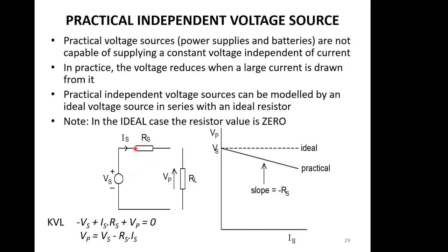And as a battery goes flat, it doesn't really go flat. What happens is this resistance gets bigger inside the battery, because the battery just has trouble getting the charge to run out of itself. So as you pull current out, you put your load, your light bulb or whatever, on the output of this source, and the internal resistance is now significant. As soon as any current flows through the battery and into your light bulb or whatever, you've got a potential divider, and this voltage here will drop. And the more current you take out, the more this voltage will drop.